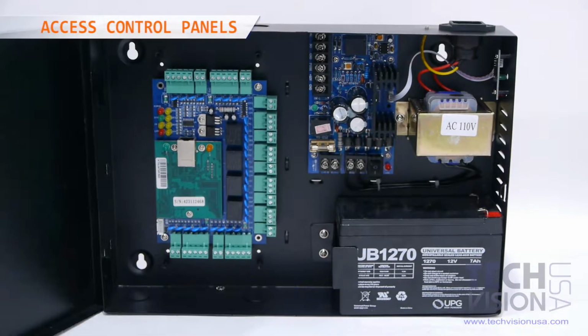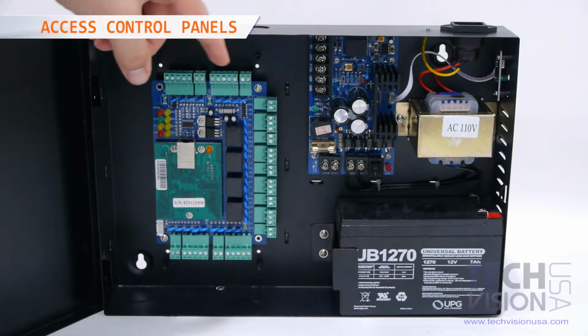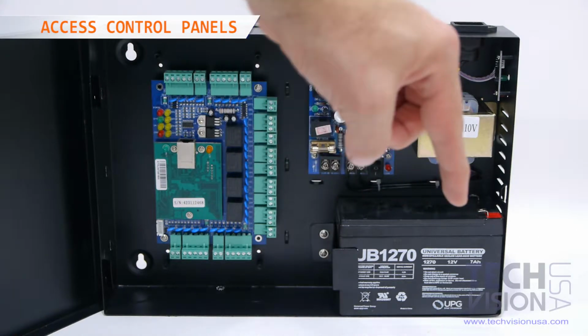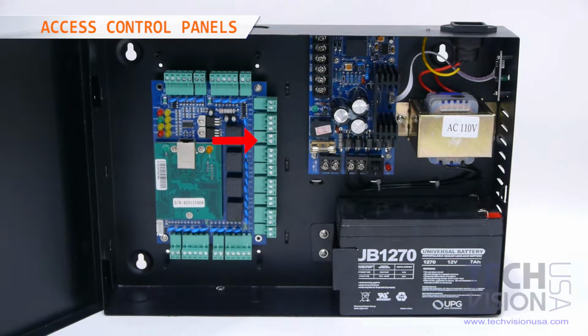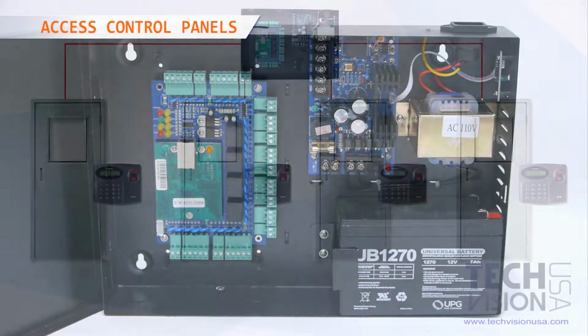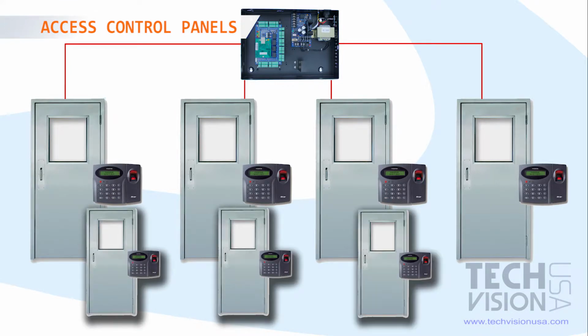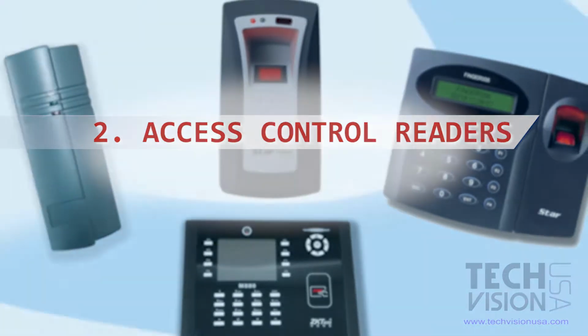Part 1, access control panels. Access control panels are essentially the brains of the system. Usually, the panel is made up of a circuit board inside an enclosed box, along with a power supply. Sometimes there is a battery backup as well. The number of access points or doors you can control depends on the capabilities of the specific access control board you use. Many come as a standard configuration, but can be upgraded as your needs change. For example, you might buy a 4-door access control board that can be upgraded to control up to 8 doors at a later time.